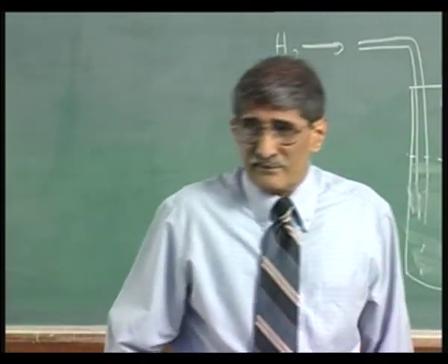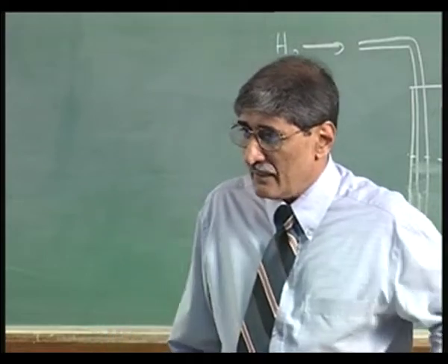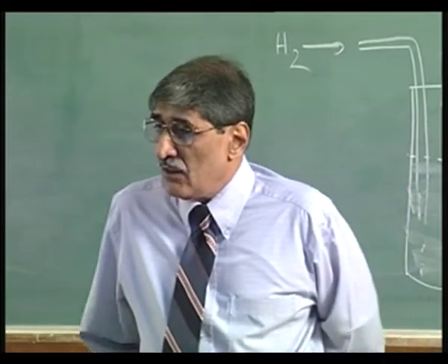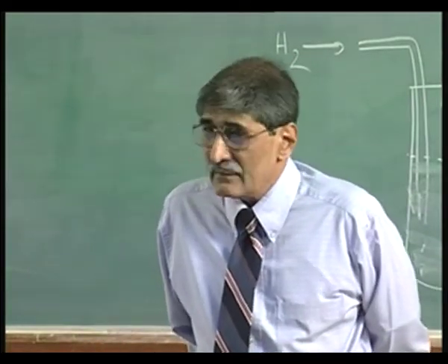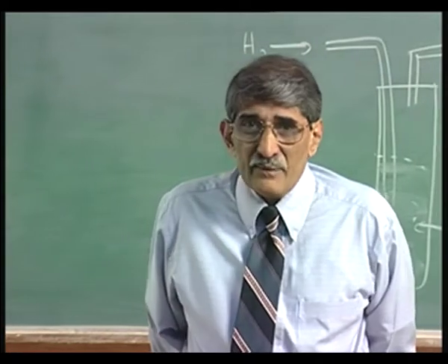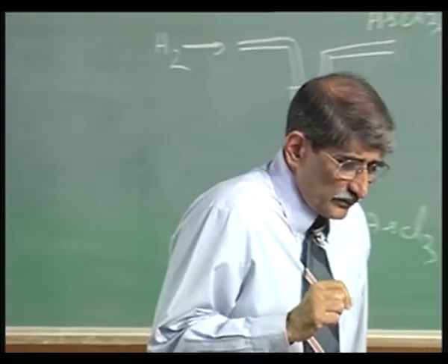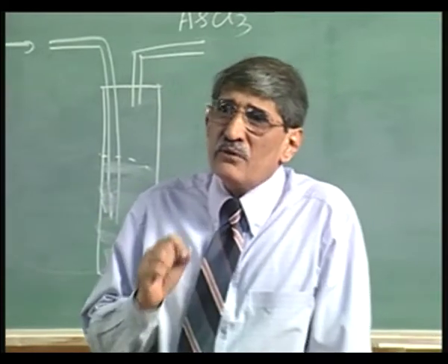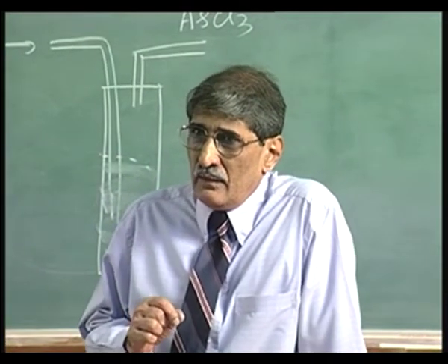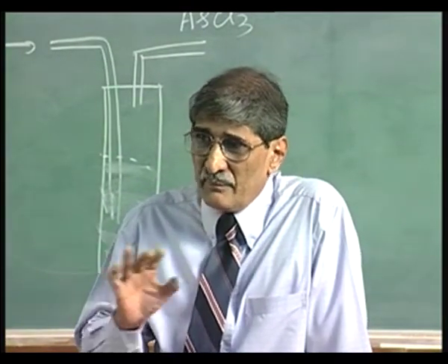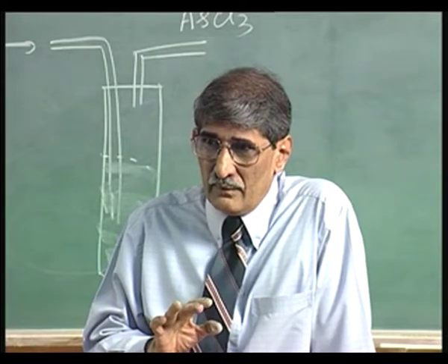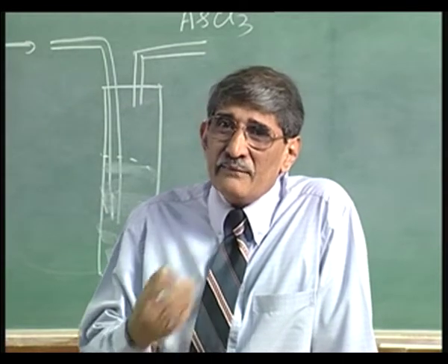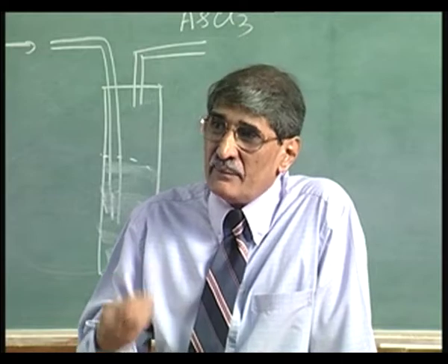Coming to the third process, that is MOCVD, or metal organic chemical vapor deposition. I just want to give a word of caution. We are talking of vapor phase epitaxy. Sometimes it is also referred to as chemical vapor deposition.